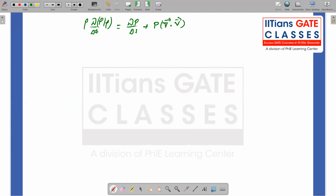Now DP/Dt I can write in terms of the temporal derivative plus the convective derivative, v · grad P, and I already have the other term, P times divergence of the velocity vector, equal to the left hand side rho D/Dt of (P/rho).